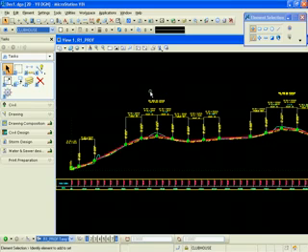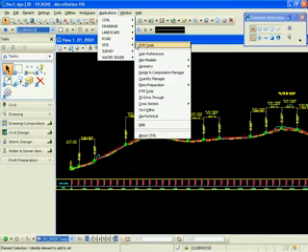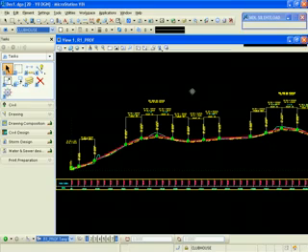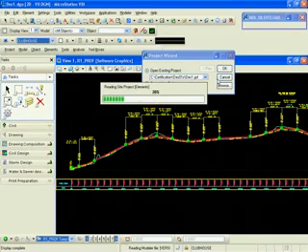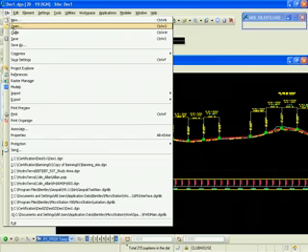To edit a DGN library using any of our civil tools, or placing any civil tool operations in those libraries, we do things a little bit differently. To begin with, in this case, I want to place Site Modeler tools into my DGN library. Prior to entering into my DGN library, I'm going to open up Site Modeler. This will make those tools active for me to copy into. Well, let's move into our DGN library.